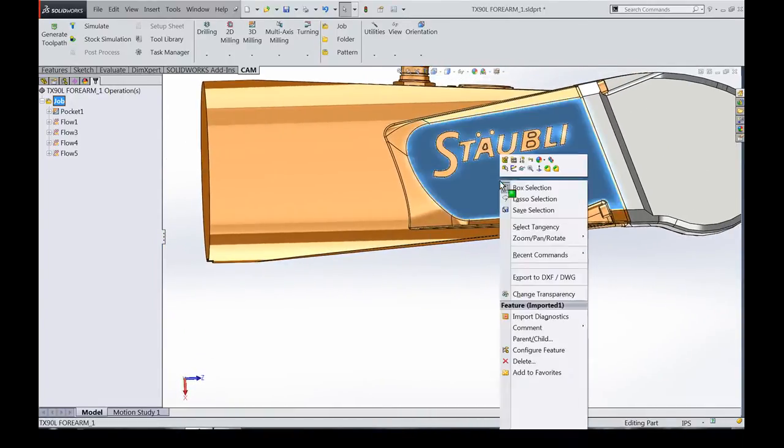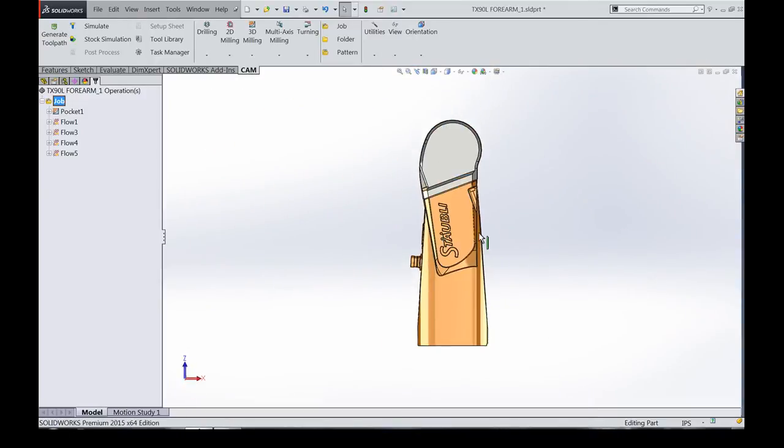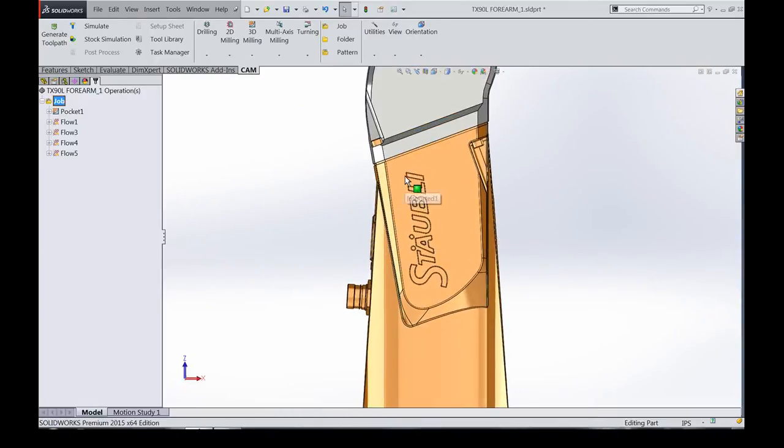Morph is still a 2D projection strategy, so much like parallel, which I discussed, it creates back and forth lines and then projects that down along your Z vector onto the model. Morph does the same thing, only rather than doing straight lines, it has you input some guide curves and then morphs between those guide curves.